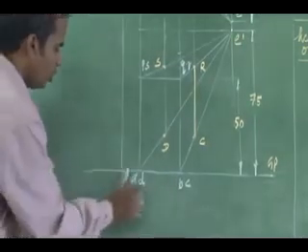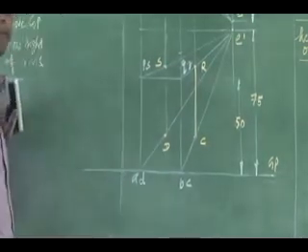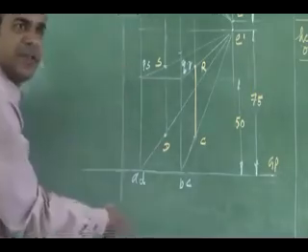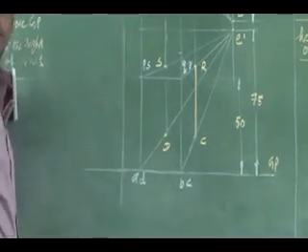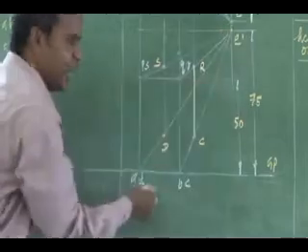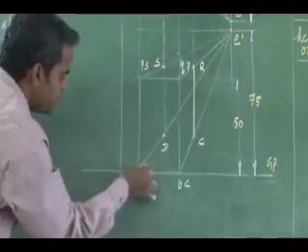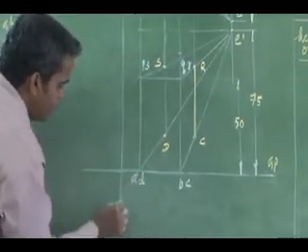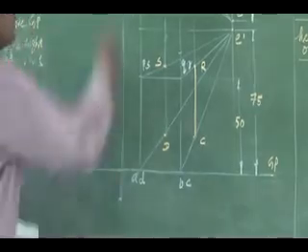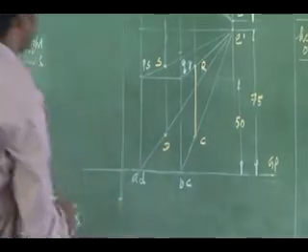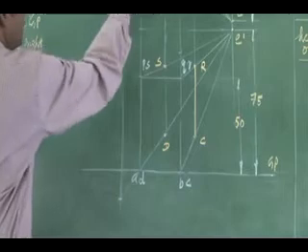What do I have to do to get the perspective location of A? I have projected the AP intercept. Just extend the visual ray line of your front view in the same manner, to where it meets the corresponding intercept projector.